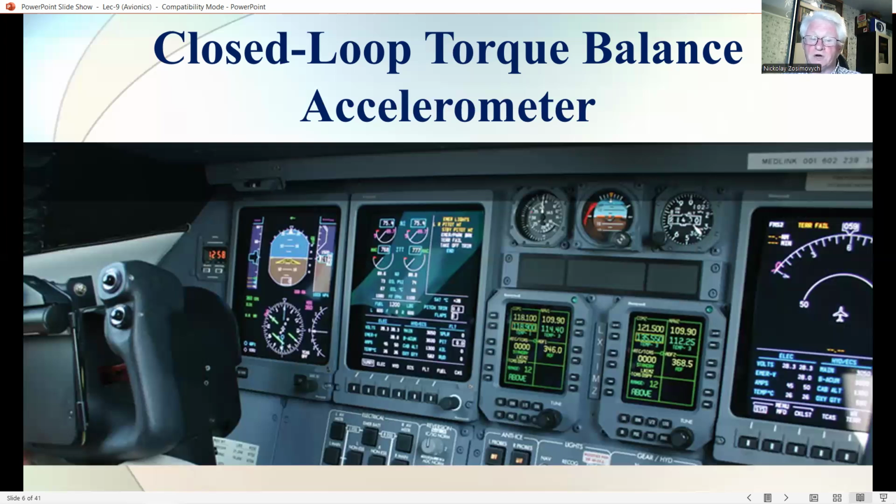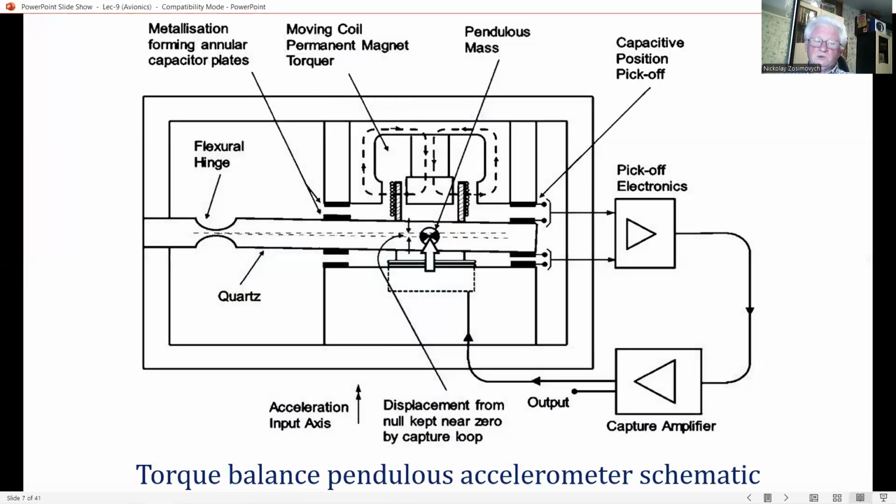Measurement of the torque exerted by the torque motor to balance the inertia torque resulting from accelerating the pendulum's mass so that it has the same acceleration as the vehicle, then enables the acceleration to be determined. Strictly speaking, the specific force is measured.